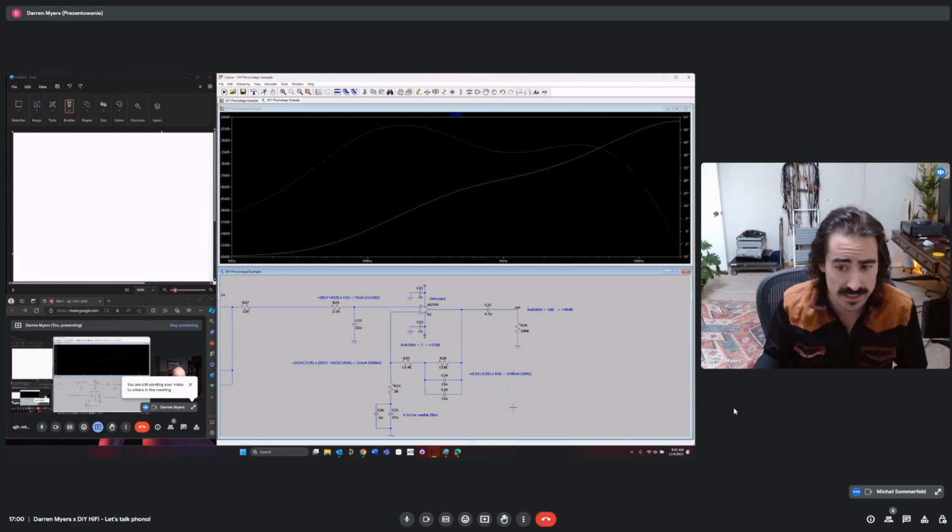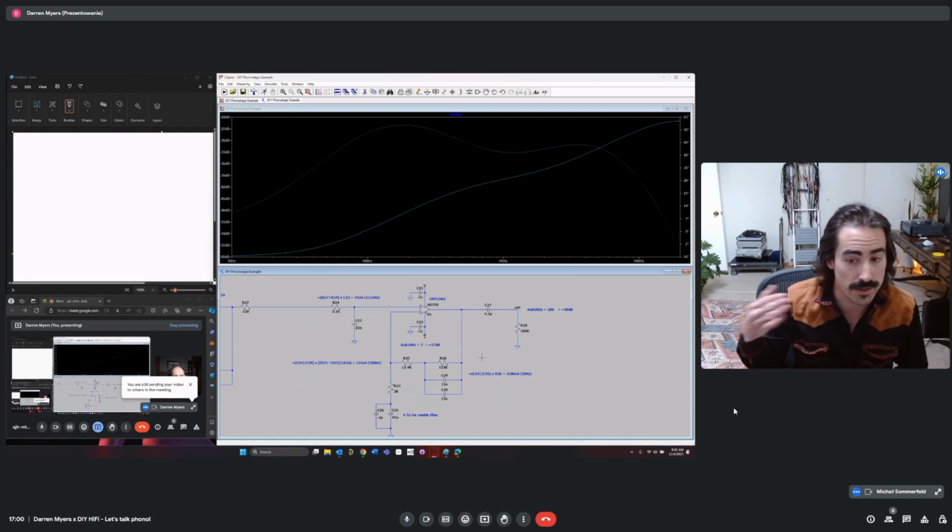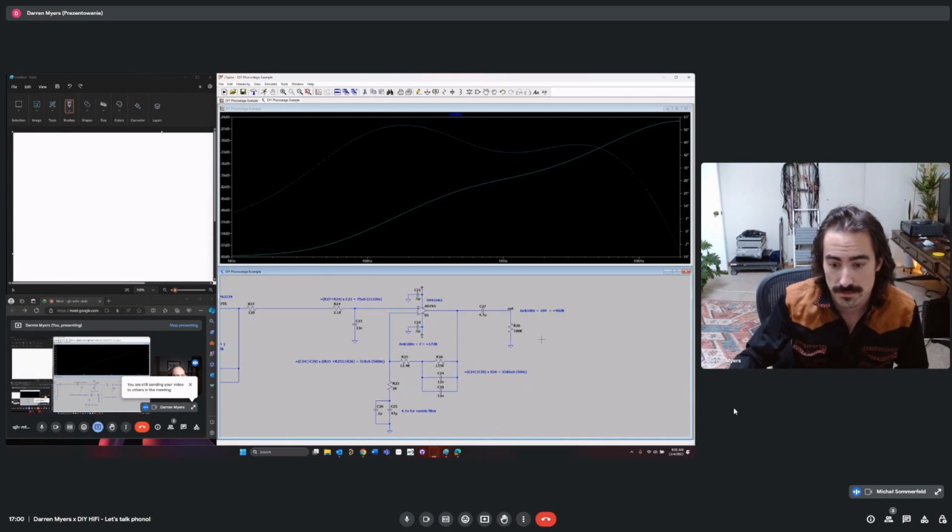So that dramatically reduces our DC gain, and it's going to help us not run into massive DC issues, because without much care you could easily end up with volts of DC here, and we all know that won't be good. That will cause early clipping, and you really want to run these amplifiers where their output is close to 0, so that they have equal headroom on the top and on the bottom. Why not do it in the first stage?